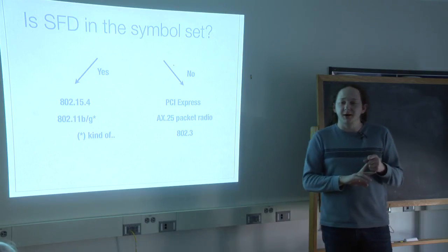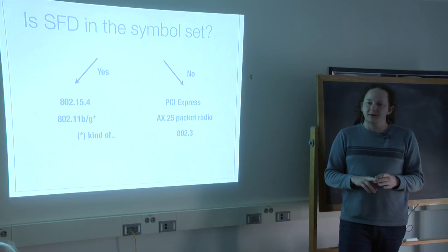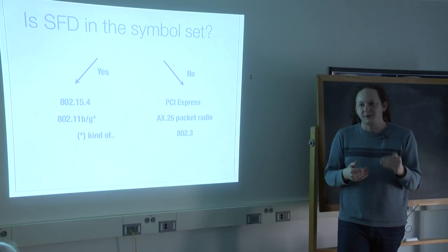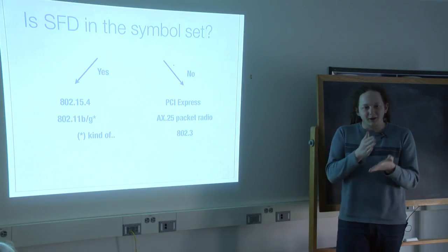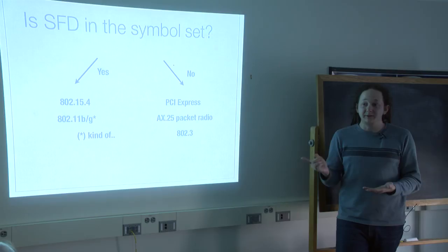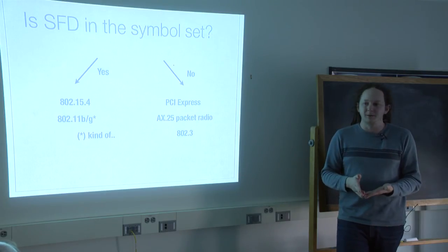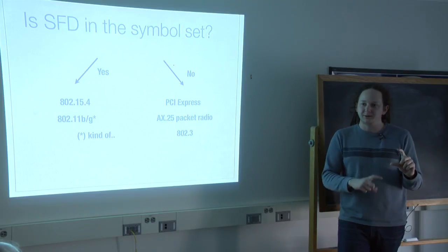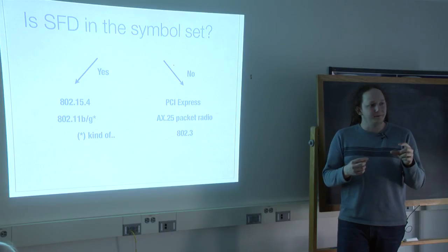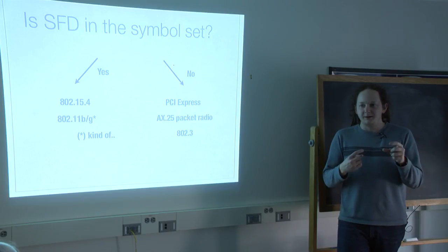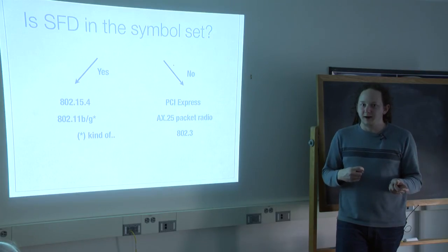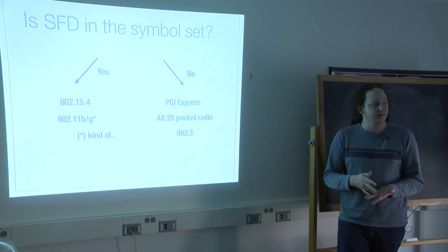One of them is a no-op that actually means nothing, but will get stuffed into the packet whenever the transmitter needs a little bit more time. And also at regular intervals, so that the receiver can cut them out whenever it needs a little bit more time. And that way, if the PCI Express card and the PCI Express controller are running at different clock rates, they don't collide by not being able to populate their memory fast enough. And this saves them from having to have twice the memory speed of their bus speed.